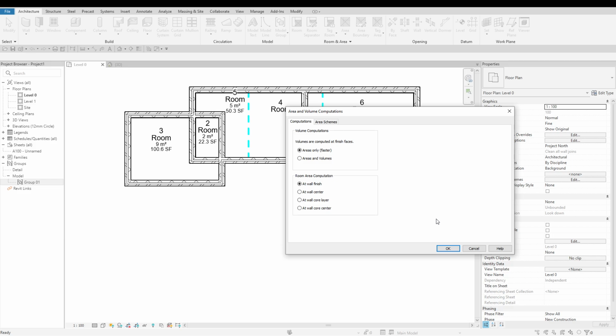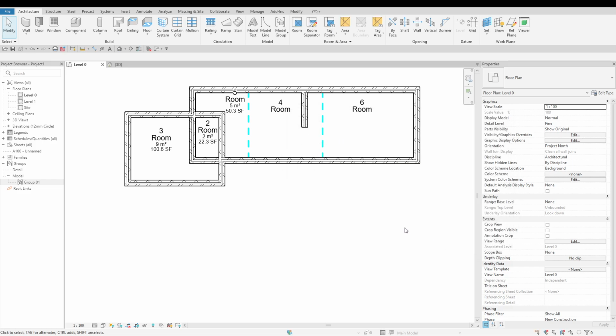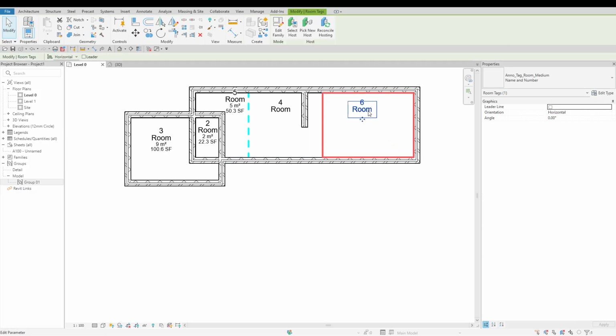The room component plays a key role in maintaining data for the area where it's placed. It stores various parameters that influence important factors like heating and cooling in your project. For an accurate energy analysis, it's crucial that every area in your model is defined by room components, and that the entire building volume is accounted for.